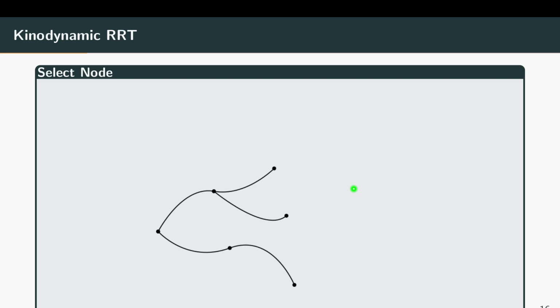First generate a random point, and then find the nearest neighbor, and then try to step forward a small step. Exactly. So we sample that random point. We find the state that is closest with respect to some metric, so so far everything is the same.